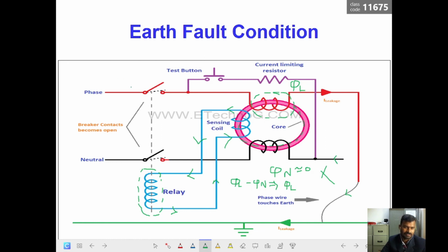So what is the basic difference here? The MCB is comparing the rated current and the line current. When the line load current exceeds the rated current, the MCB will open. Here, the RCD is not looking at the line current or the load current. It is the earth fault detection in the RCD, and it is always comparing the input current and output current.